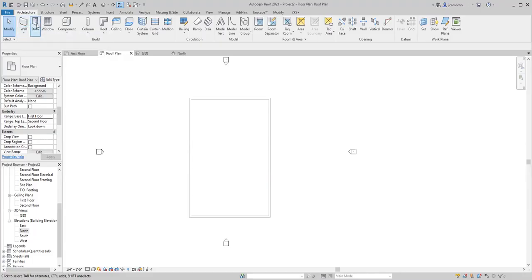If we wanted a wall, we go to walls. We want doors, we go to doors. Components, windows, roofs, ceilings, floors, right? These are all elements that are predefined in a lot of ways. We could go in there and change them, but a roof is a roof, a floor is a floor in Revit. When we go into in-place massings, it's just a block, right? And we get to design and shape this block however we want to, and then we get to bring it into the actual model itself, right?